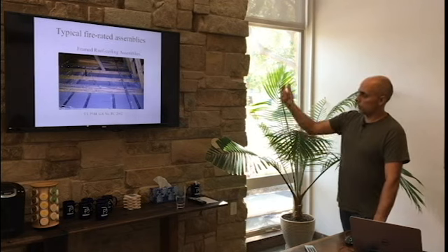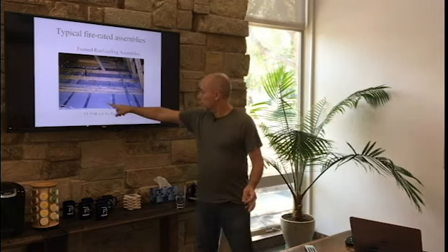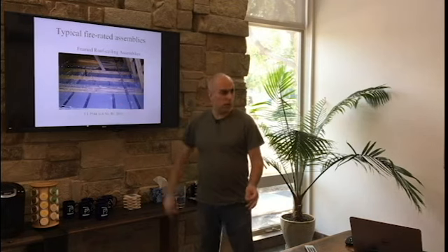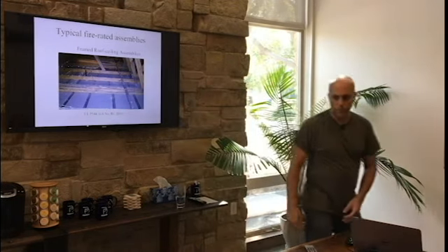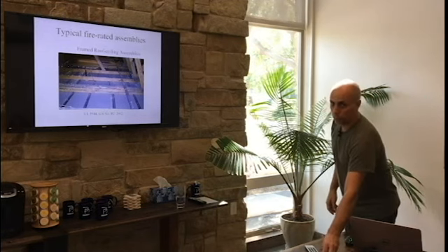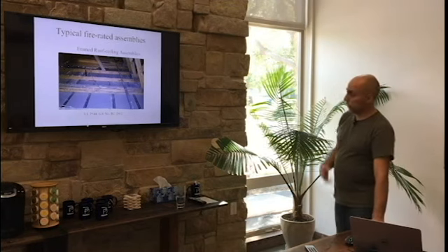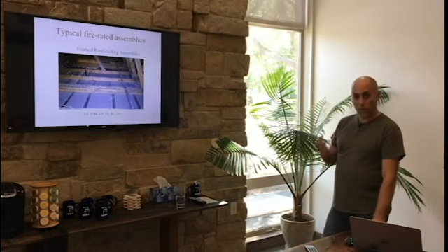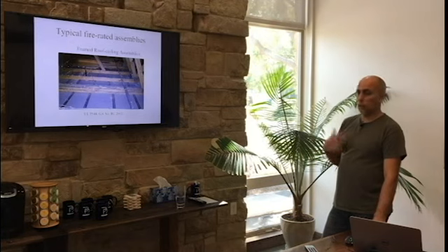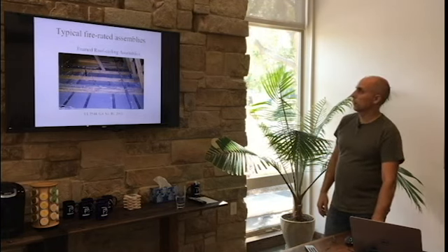The channels are screwed in, and this is how you can always tell whether or not they have the right board up there: look for that UL stamp. It's on the back of every single board. If it doesn't have a UL stamp or it has the wrong one, you've got a problem because you've got the wrong board and don't have the right assembly anymore. Now you have to either make sure you have an assembly that matches what you have, or you may be ripping something down or adding something to it to now meet a tested assembly.